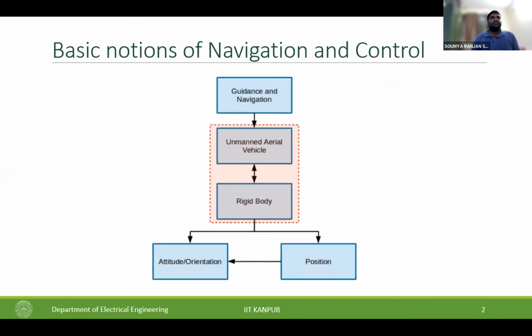Okay, so as far as quad rotors are concerned, their control is based on the usual rigid body models. And since, as the name suggests, there are 4 rotors in a quad rotor, they are basically under-actuated systems. So what you would like is to control the position and the attitude of this particular vehicle, but because of under-actuation, the XY motion of such a vehicle essentially gets coupled to the roll and pitch of the vehicle.